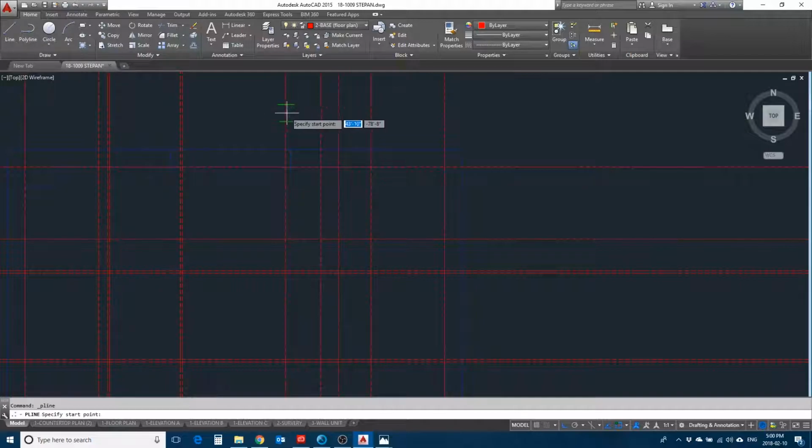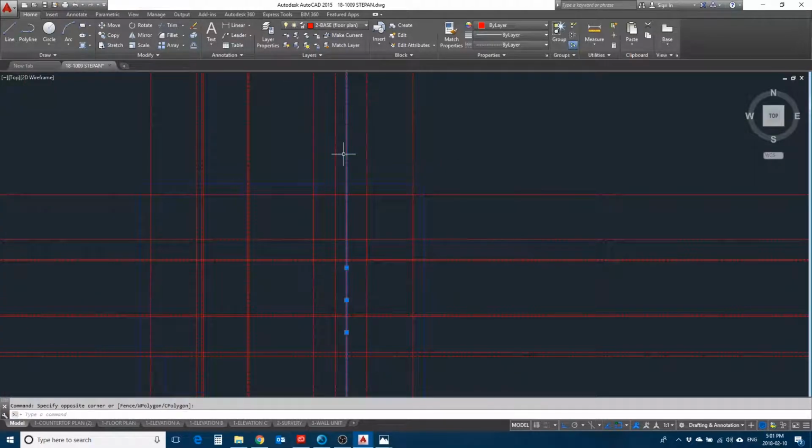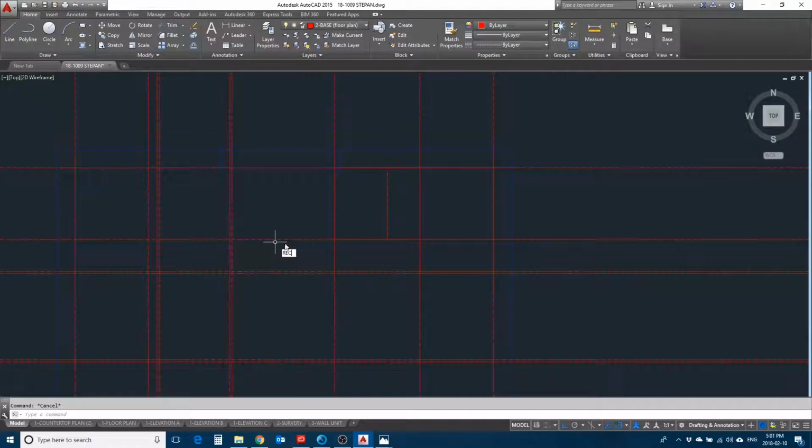it's not too complicated. So let's start with the corner cabinet. You can do it one at a time, but just to show you how it could be done. Now a rectangle for these guys. So I'm done with this line and this line. R, enter or space.